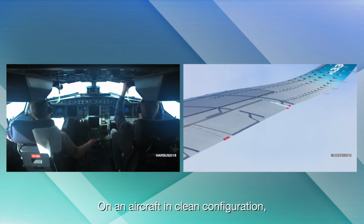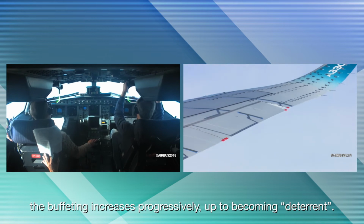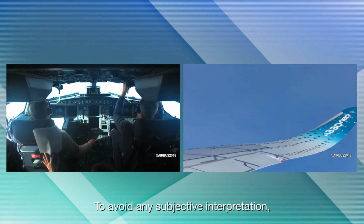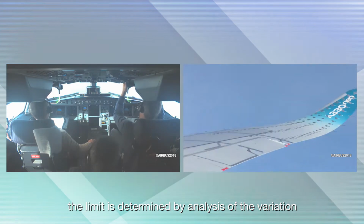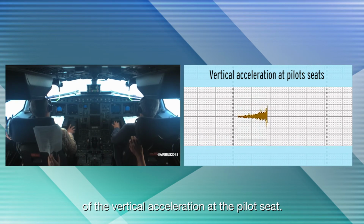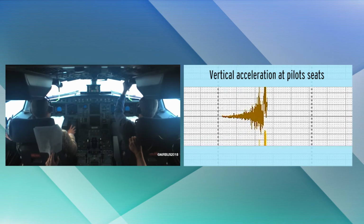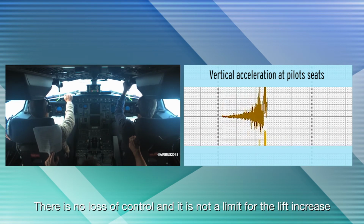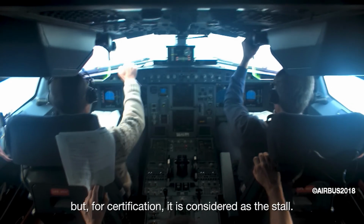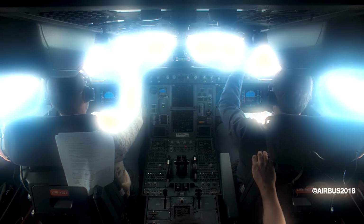On an aircraft in clean configuration, the buffeting increases progressively up to becoming deterrent. To avoid any subjective interpretation, the limit is determined by analysis of the variation of the vertical acceleration at the pilot seat. There is no loss of control, and it is not a limit for the lift increase, but for certification, it is considered as the stall.